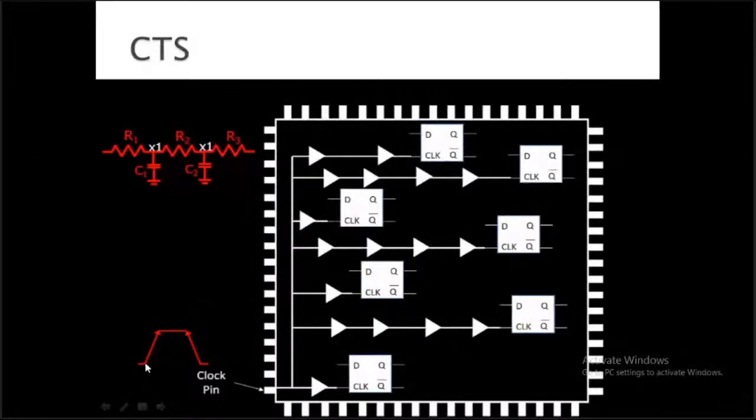You can see, in the real world there is no ideal clock. We have some transition at the input, and this transition is going to increase with time. Because if you see this wire at the resistor level, the RC level, these are the parasitics of the wire. It will look like this, RC in this way. So this transition can change from here to here. It may become more slow, or it may happen that the clock is gone. So we have to decide the minimum width of the clock as well, and the connectivity path as well.